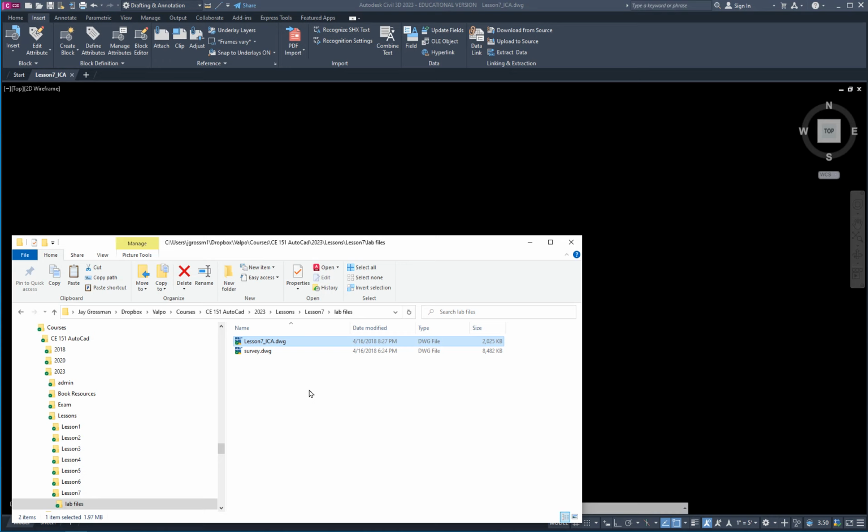We want to do our design in the same file because we don't want to mess up the surveyor's file, because that's theirs. They measured everything in the field and created this file for us as a good background. We don't want to accidentally delete things out of it that we wouldn't know how to get back, or not realize that we deleted things out of it. So we use it as an Xref, and it's a layer of security we've got in our files.